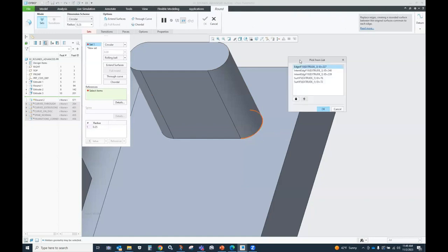And here you'll see that we have the edge, of course, the surfaces that were behind my cursor, but then we have this intent selection here, and its ID is 240, and then we have this intent selection here, its ID is 239. They look the same, don't they? It looks like the same geometry is being selected. Why would there be two? Well, the reason there's two is because there's two different behaviors for these intent selections. They look very similar. However, they have different IDs, and they do in fact do different things.